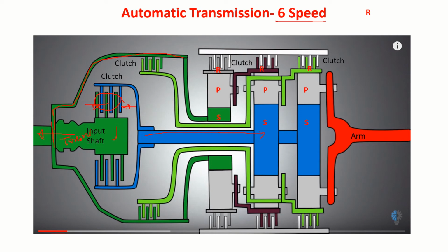Now you see here, I have one epicyclic gear train system. Say this is the sun, this is the planet, and this is the ring. So over the ring gear, you have clutches. Correct? And as you have seen in the previous figure, these clutches can be operated using that hydraulic power. Correct? By applying the brakes, using that hydraulic power, we can engage these clutches.